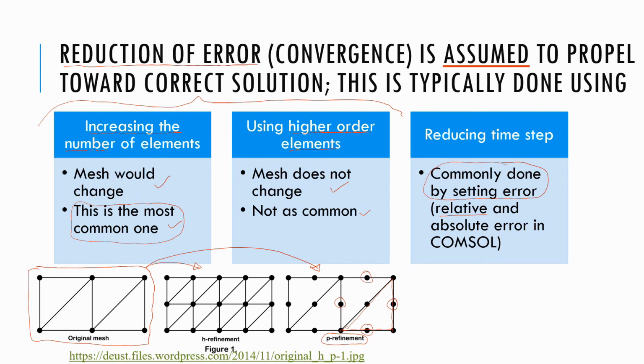So you set the relative and absolute error in COMSOL, and the program takes a time step, calculates the error, and makes sure the error is less than this, in this case in COMSOL for the temperature calculation.